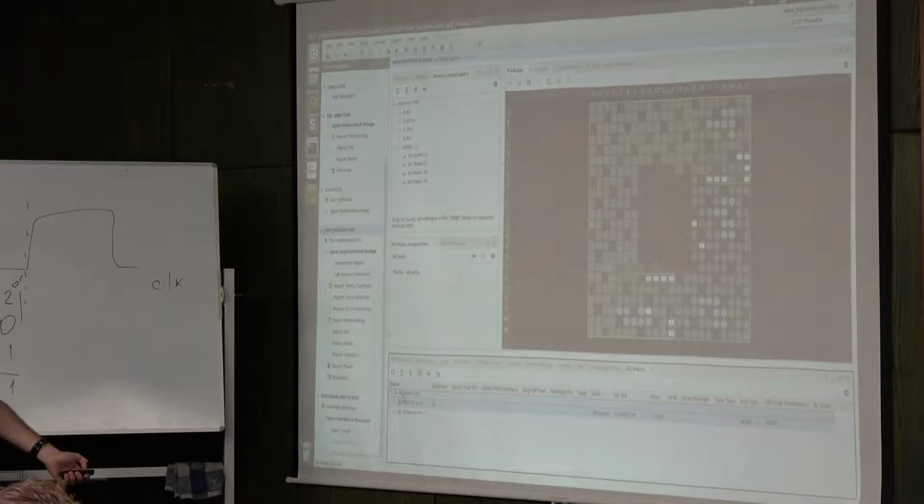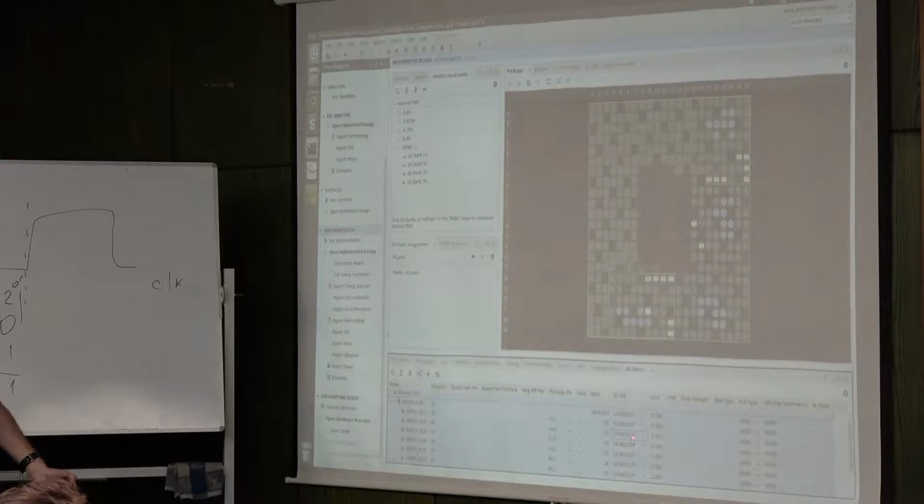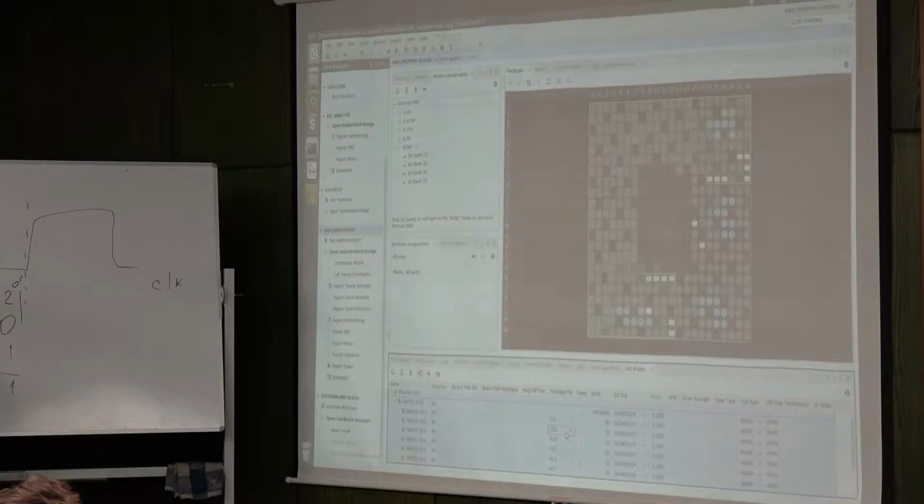This is all ports of your circuit here. Let's say you open the interface that corresponds to your switch. You define the technology, so we use 3.3 volts, and you define the pin that you want to assign to this interface. Once you do it, your constraints file will be updated, and this is how you map pins of your circuit to the pins of the chip.